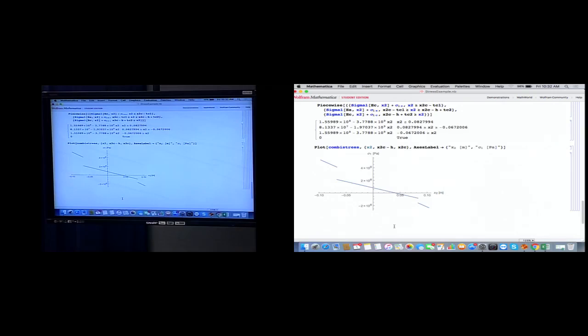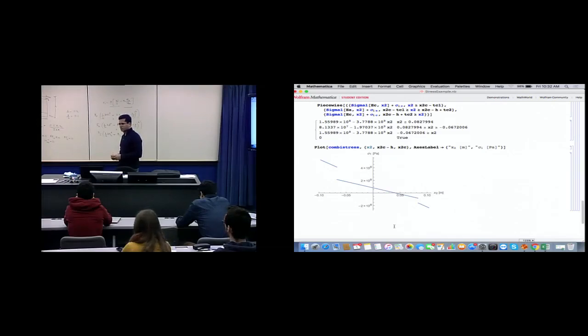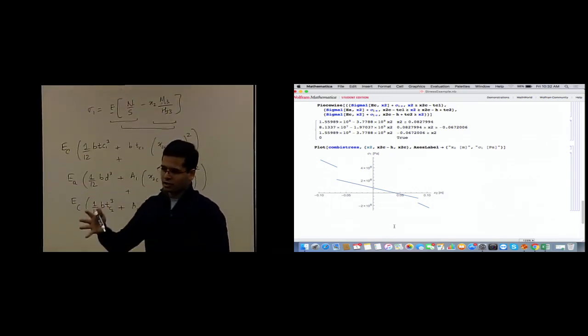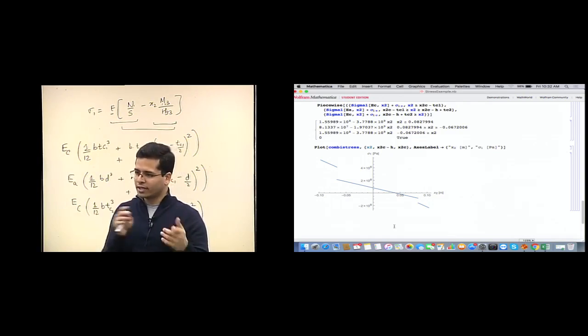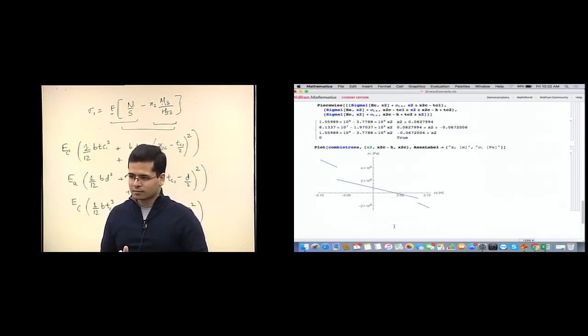So sigma 1 in the top layer would be the EC times the entire N1, the entire axial load applied over the... Yes, because this quantity represents the strain, and that is calculated for a section. And then you multiply it with the material property of the layer to identify the stresses in that section.